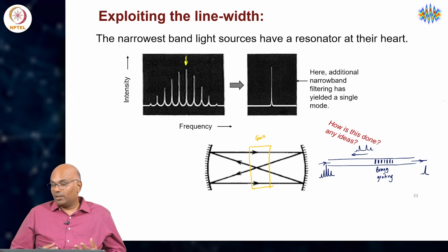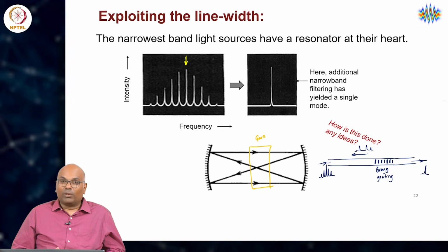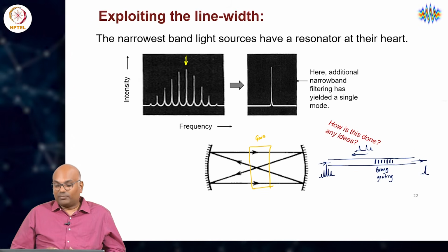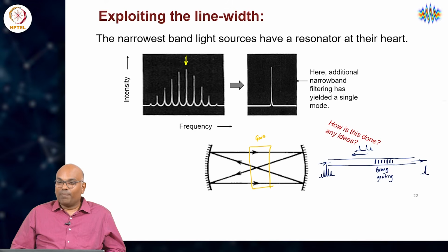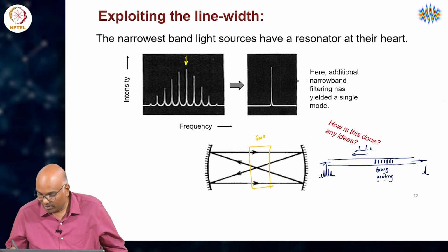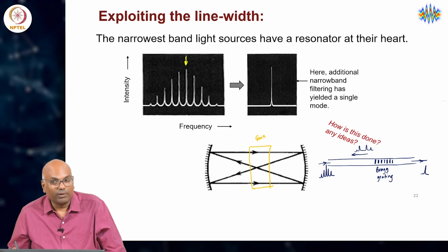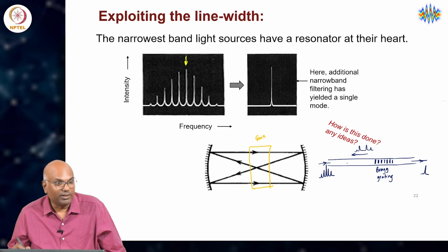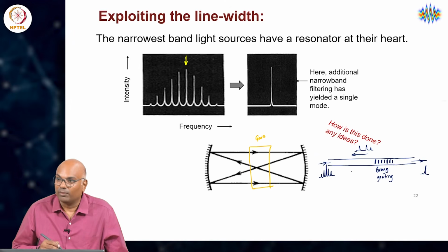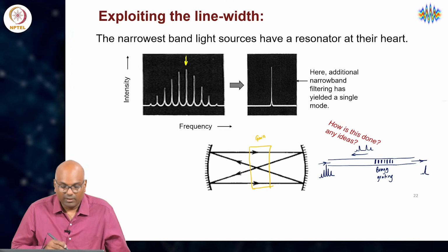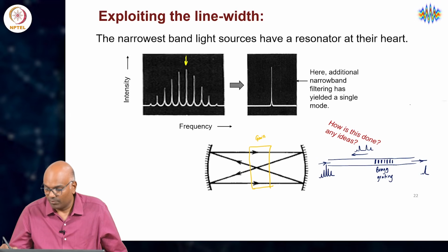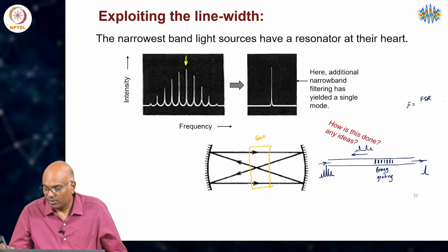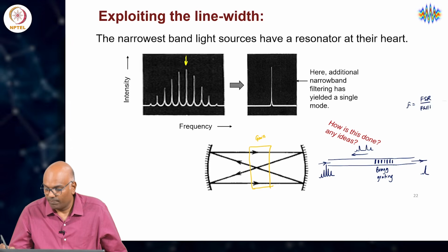Excellent points. I am so glad that you are coming along with nice ideas. Okay, however, there are still points to consider. So, in principle, the Bragg grating would be able to do this provided the resolving power of the Bragg grating device is better than the resolving power of the Fabry-Perot, or the finesse, right. So, the finesse of the Fabry-Perot was FSR by FWHM.